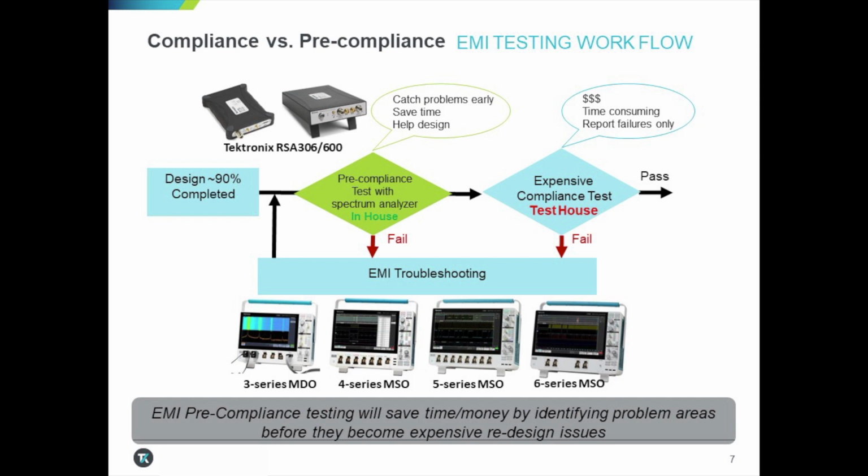Performing some practical and easy-to-perform pre-compliance tests will save time and money by identifying potential failures early before they become expensive redesign issues. While the use of pre-certified RF modules simplifies much of the design, as was the case in the previous slide, it won't remove all requirements for EMI or EMC regulatory compliance testing. Many IoT design teams assume that EMI testing is a mere formality. Unfortunately, this is rarely a safe assumption.